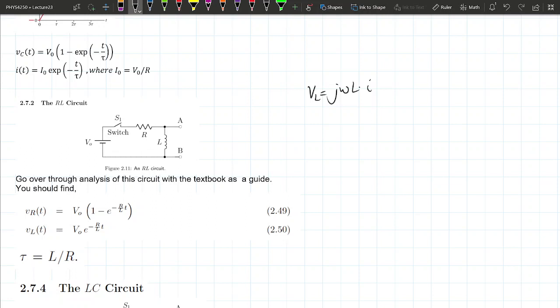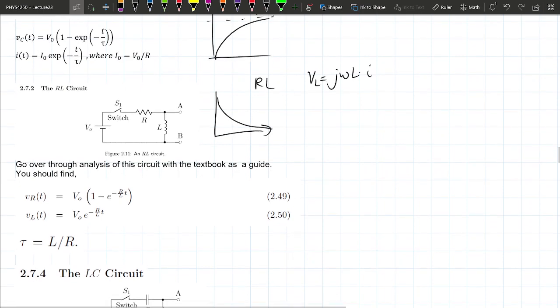instead of a growing exponential, actually a growing exponential with a little limit on top. This is for the RC. If you have an RL circuit, it'll be an exponential decay instead. They kind of behave opposite of each other, and we're going to see this. That's why you have both devices. That way you can have something that causes charge to collect, and something that causes current to change slower. That's just the way to think about it.